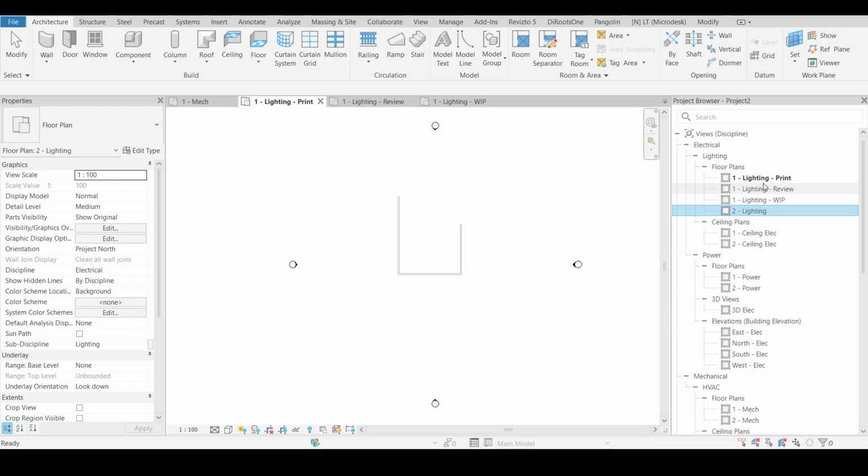If we try to put all these services in one model, it will become extra heavy and will downgrade your productivity in Revit. So what we normally follow is we create one model for one discipline and link the rest of the disciplines into it and work. Suppose you are doing electrical services, you can have electrical, lighting and ELV, all three. So we have to create the three view types for all levels. Let's say we have 10 levels in our building, so 10 floor views for 3 disciplines: lighting, power, ELV.